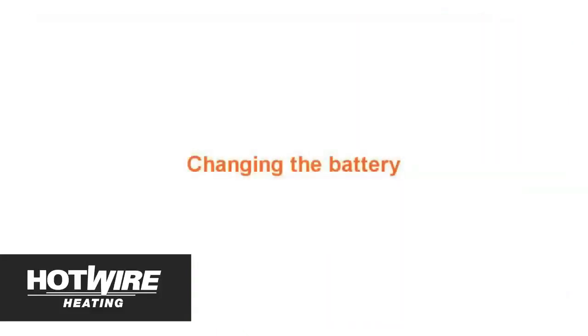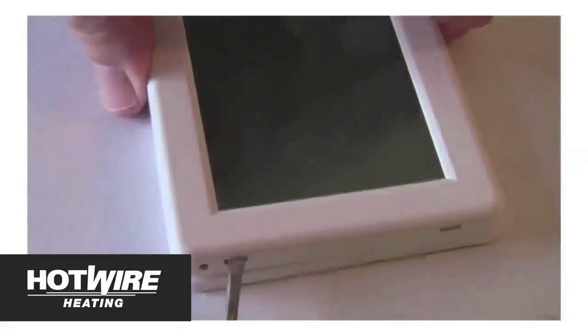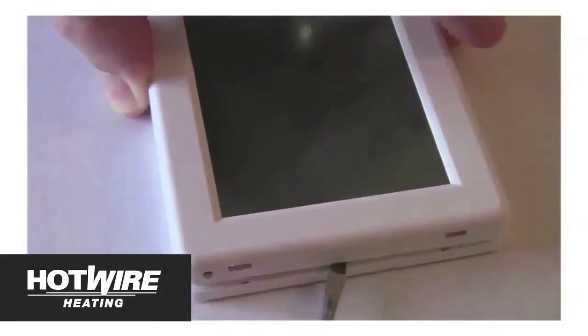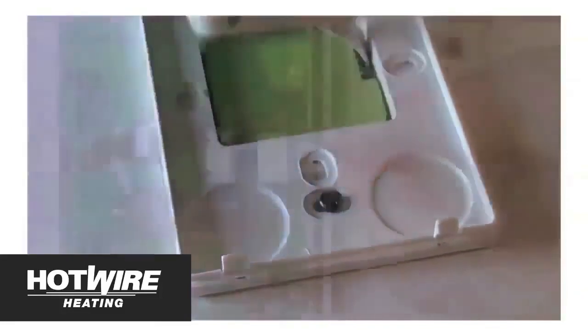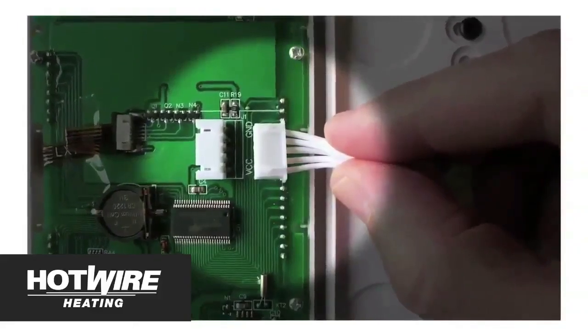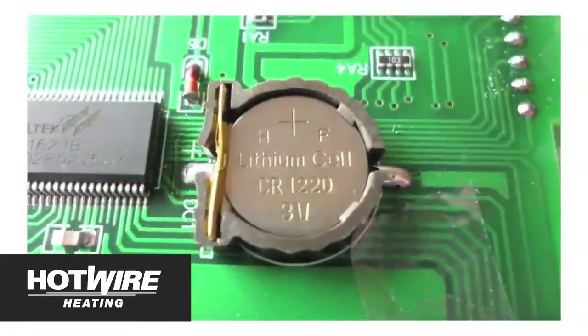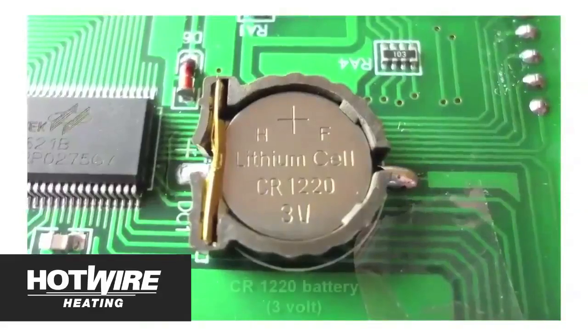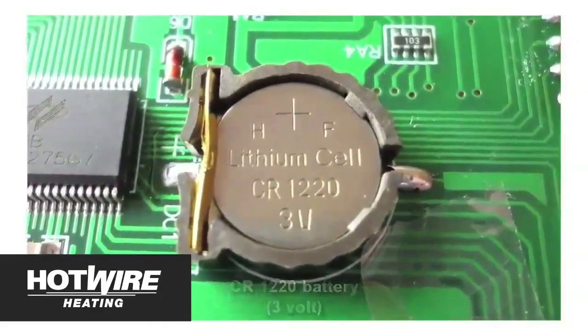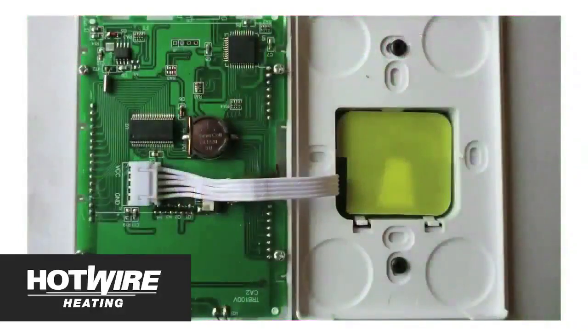Changing the battery. To change the battery on the thermostat, use a small flat-headed screwdriver to pry the unit away from its base in 2 places below the unit. Then turn the unit over and remove the ribbon connector for easier access. Gently pry the old battery out and replace it with a new one. The unit uses a CR1220 3V battery. When the new battery is in place, reconnect the cable and clip the unit back into place.